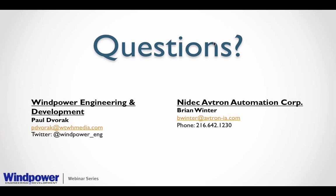I've seen the classic design is the German one with an absolute encoder with 8192 counts behind a 27-to-1 gearbox trying to measure a blade pitch to about 1 degree. You've got an awful lot of counts there to try to measure 1 degree. It's really overkill. Yeah. Okay. Kyle asked a question here. How sensitive is a magnetic encoder to EMI?